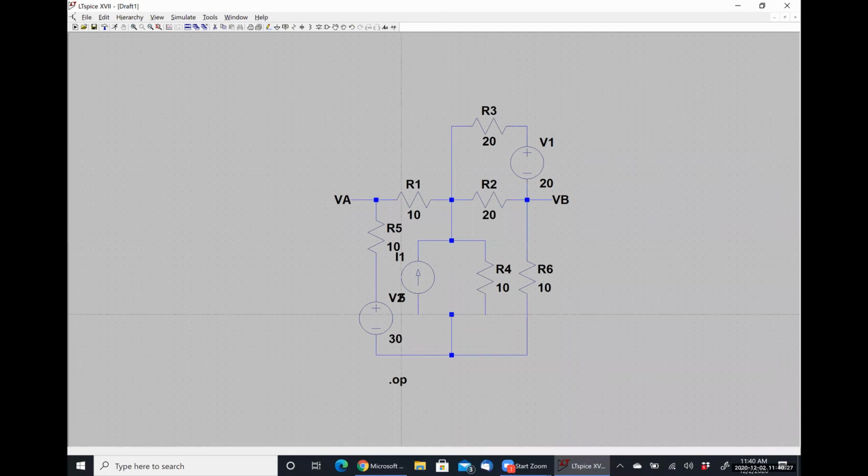So we just need to choose a ground. I'm arbitrarily going to choose the bottom. The reason I'm putting this little stub of wire before I connect ground is that, for some strange reason, in some circuits, if I connect my ground to that bottom rail, it freaks out and gives me weird answers. So I make a little stub to designate that that is ground.